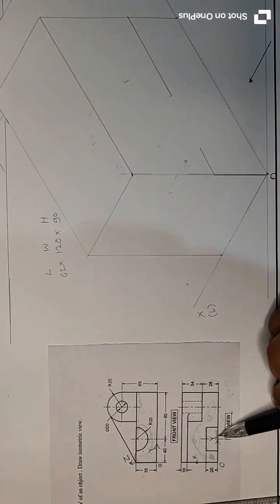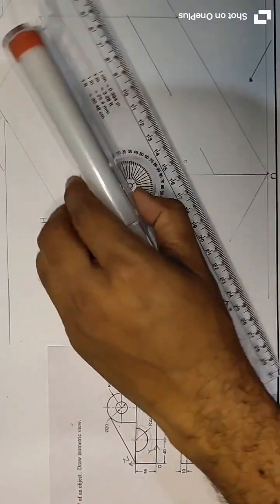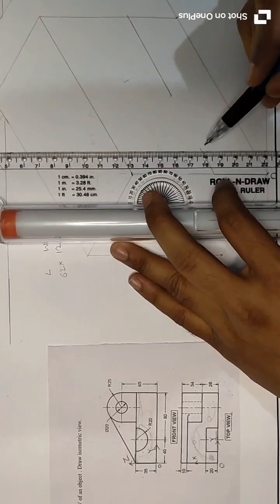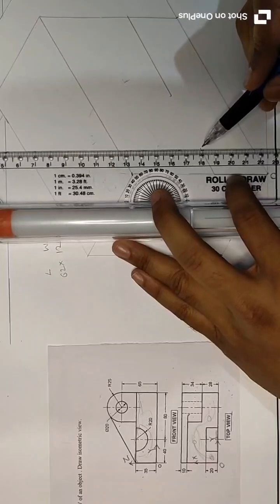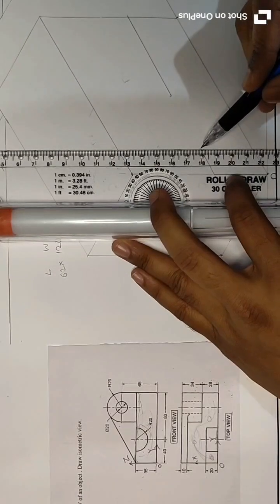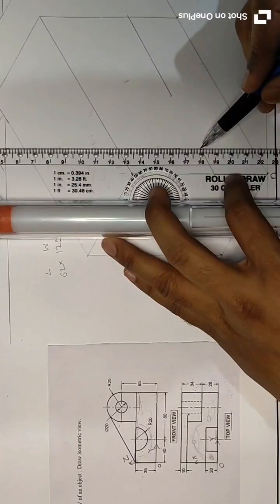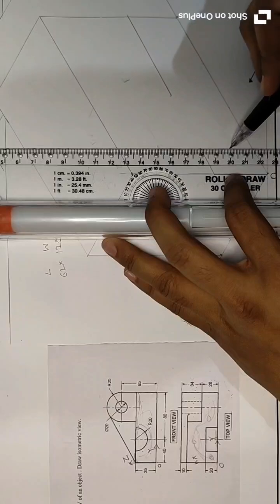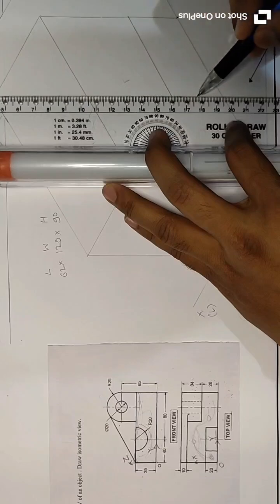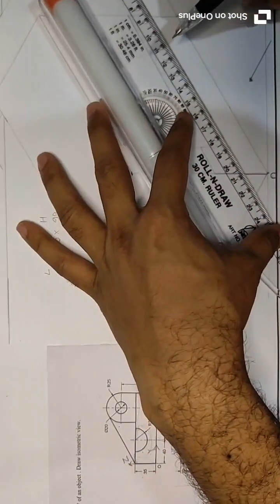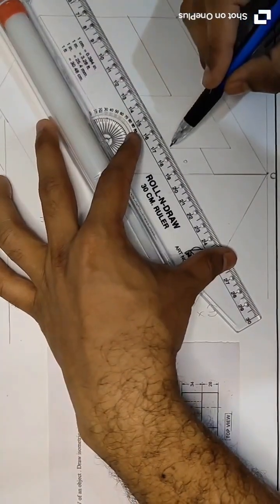Now here it is a semicircle of radius 20, that is diameter 40. So from this point, for a semicircle, we have to draw a rhombus of 40 by 40. From this point we take lines parallel to the z-axis, 2 centimeters upward and 2 centimeters downward. Draw faint lines. Also from this point take 2 centimeters upward and 2 centimeters downward. This rhombus is used to draw a whole circle, but we only want a semicircle.